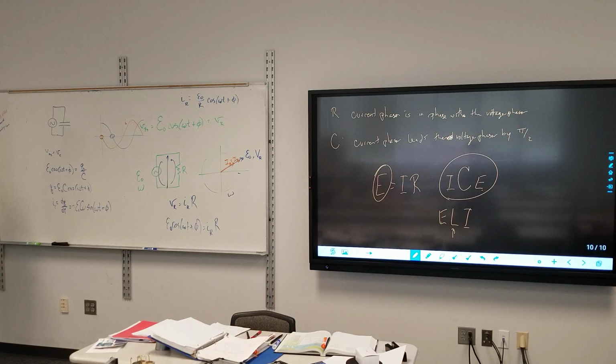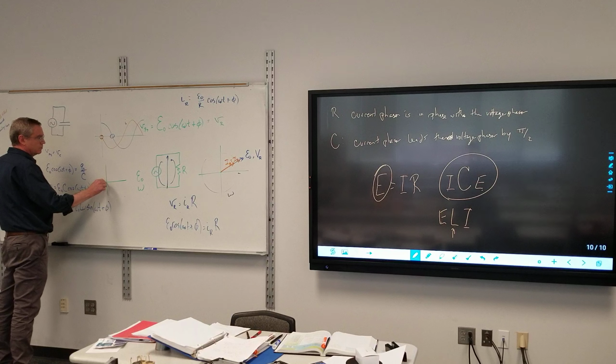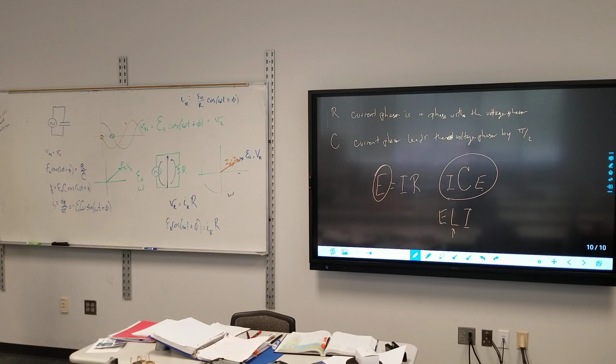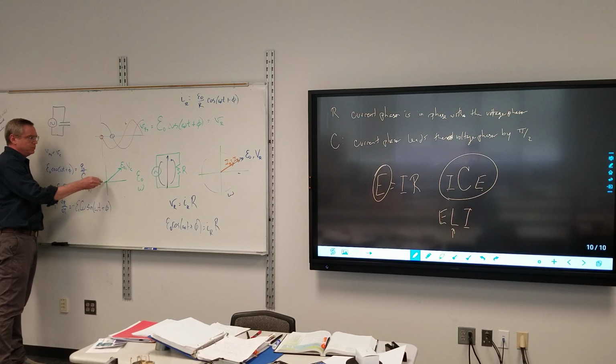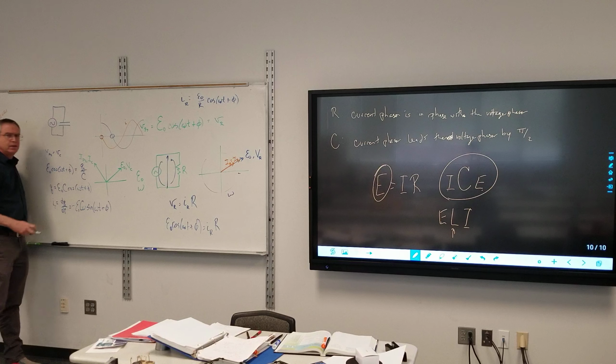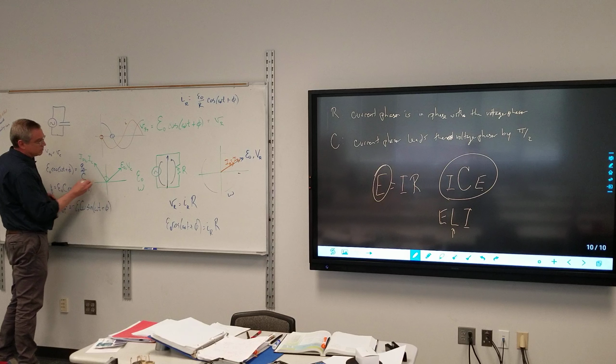So on the phasor diagram, would it just be on the opposite side? All right, so first off, we have epsilon sub naught and V sub C. The current leads by pi over 2, so my current phasor would be over here. That's 90 degrees.